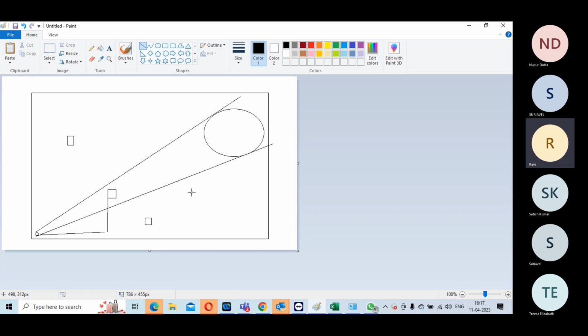You understand? I'll explain why at a later stage. But clock gating should sit close to the flop. Then what would happen is basically once this particular guy is switched off, if you are keeping clock gating too far away, all this would impact the crosstalk. Glitch will be high.